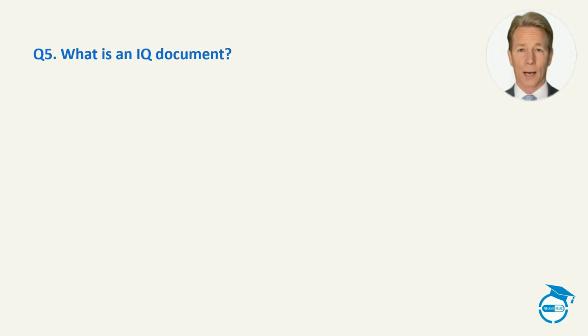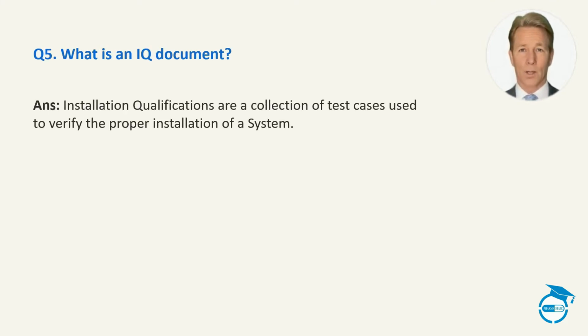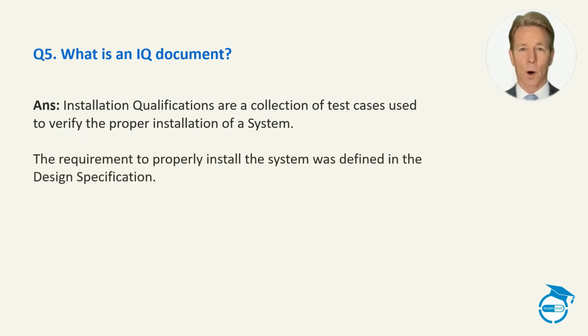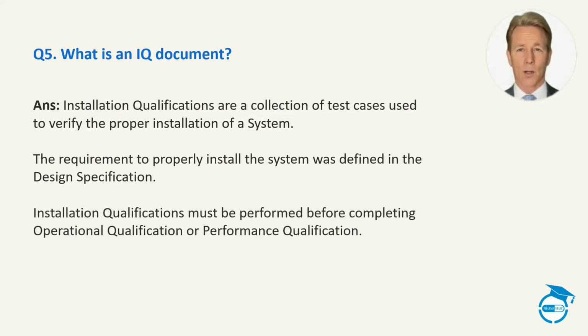What is an IQ document? Installation qualifications are a collection of test cases used to verify the proper installation of a system. The requirement to properly install the system was defined in the design specification. Installation qualifications must be performed before completing operational qualification or performance qualification.